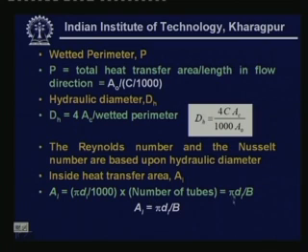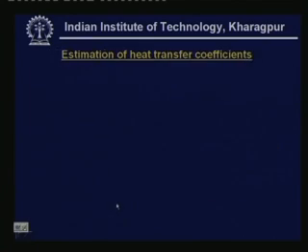So, this simply becomes pi di divided by capital B. Okay. So, this is how we can estimate, if you know the center to center spacing between the tubes, fins, fin thickness, etc., per meter square per row, we can estimate different areas, okay, heat transfer areas, and we can also estimate the hydraulic diameter, which will be used in estimating the heat transfer coefficients.